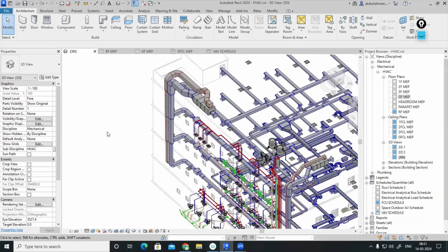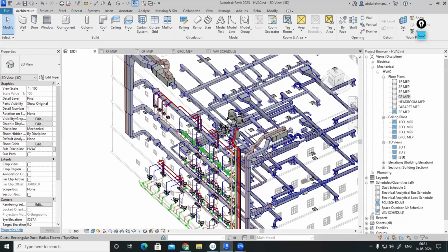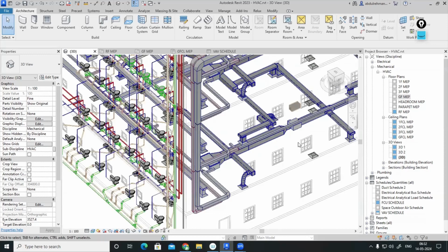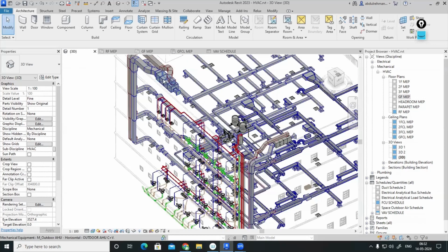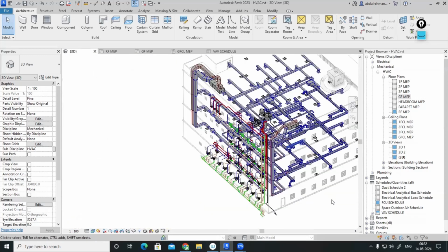In HVAC also, like air conditioning and ventilation, correct. So indoor equipment, we have placed fan coil units. Then VAV connection has been done. So this one is cooling plus ventilation for the common area. And AHU we have proposed. This is only for ventilation mixing, 20/30 mixing. FAH also we have placed.